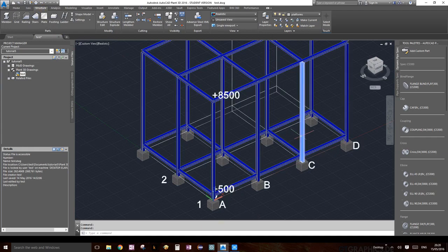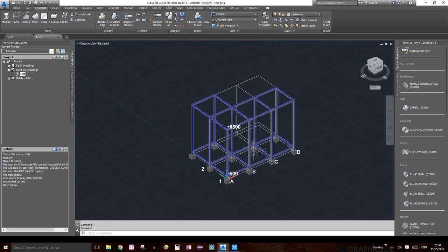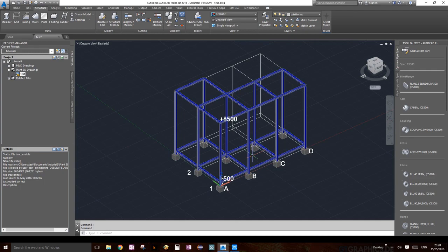Okay, so another thing that we're gonna use on and off quite a bit is the properties window. I find that it's sometimes super easy to just change the numbers than actually physically change the object. So in that case, you can just go into the properties window and quickly change some of the attributes. So to open the properties window, just as long as you're in the AutoCAD, just start typing properties.